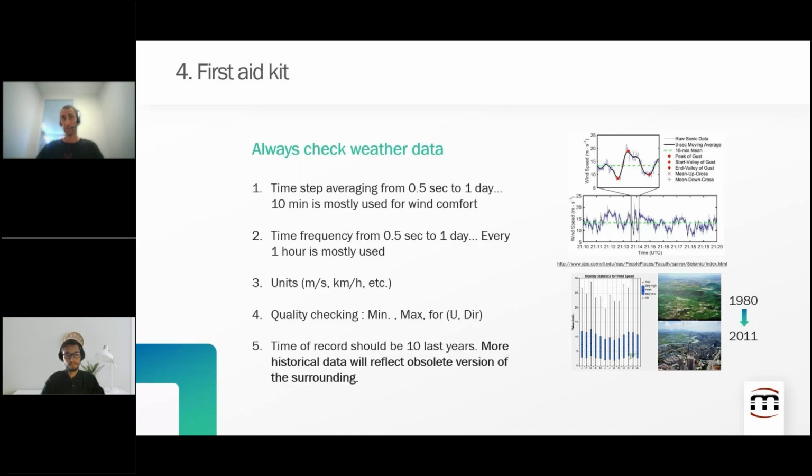This could be a case where you have a problem with a sensor, a sensor failure. If it lasts for a long time, you have to be aware it could be a failure of the sensor, so you should get rid of that in your data. So always have a look at the mean and the max of those columns.